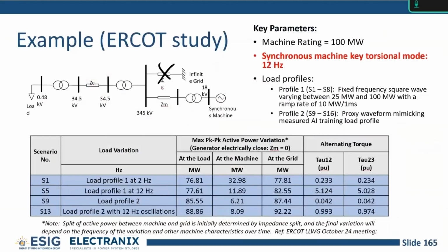Much worse for the synchronous machine, but you made it a lot better for the grid because the grid is gone, right? So one of the answers to this is, yeah, please take your system off the grid. And then, you know, good luck to you. That's a little bit cynical, but it's important to recognize that that is better for the grid, but probably much worse for the synchronous generator because now you don't have that split of impedances between the synchronous generator and the load or the system.